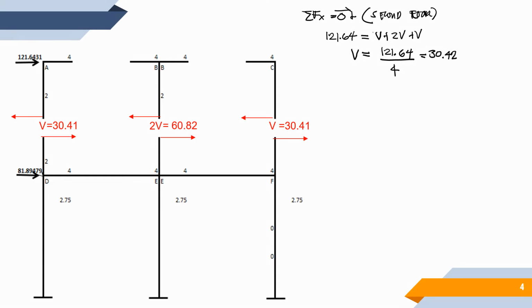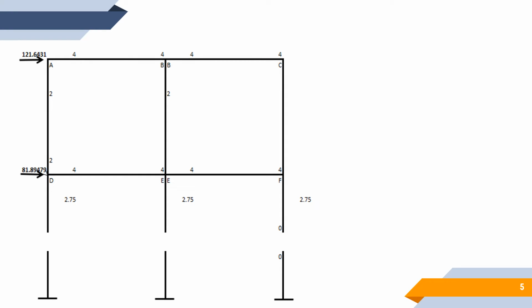So now let us proceed to the first floor. So same concepts, same assumptions will be applied. So if we have shear, but this time we already have 2 shears that will be resisted by these columns. We have this one and that one. So those that we did not cut on the second floor, those are what it considers. So, same assumption, the shear force that will be carried by our interior column will be twice that carried by the exterior column.